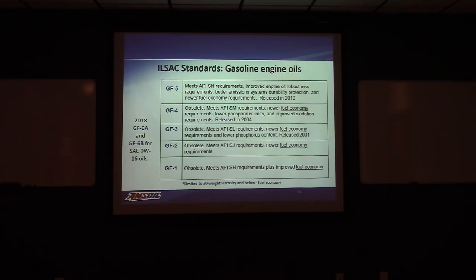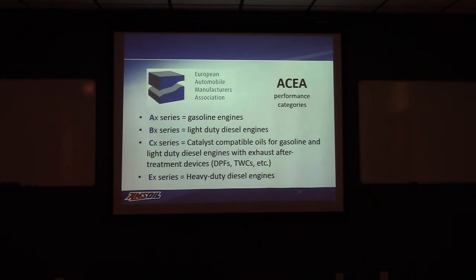GF5 is the latest, but we anticipate seeing a new GF6 being introduced sometime in 2018. That's going to be divided up too, in the normal grade oils, the 0W20s, 5W30s that we talked about before, but also to take into consideration the new SAE 16 grade, even lighter oils.